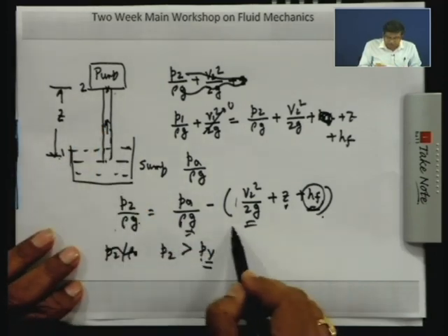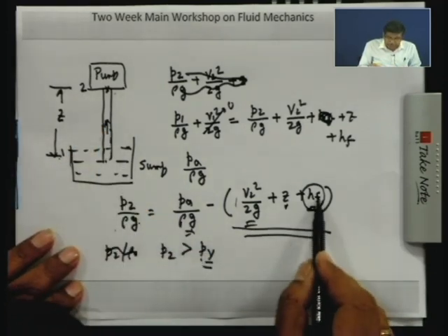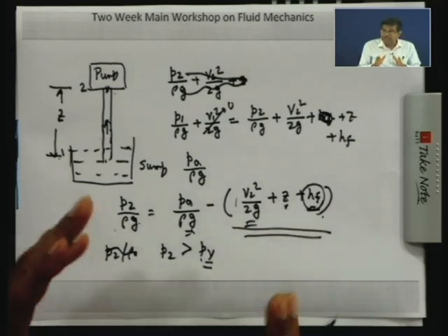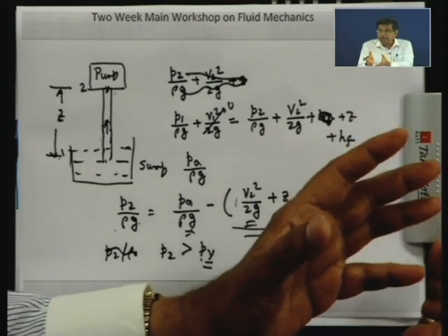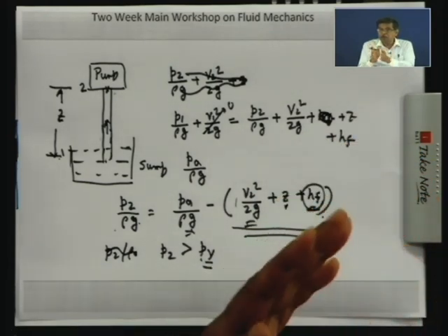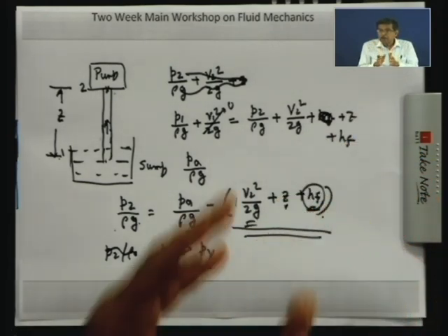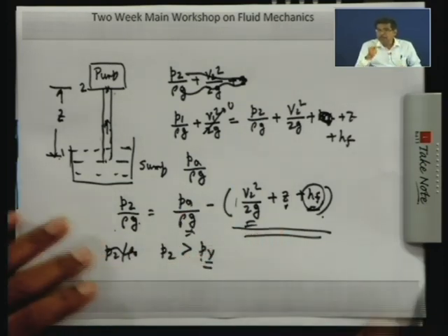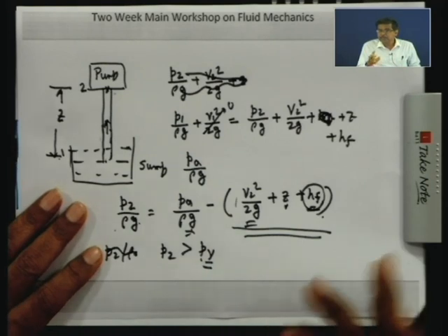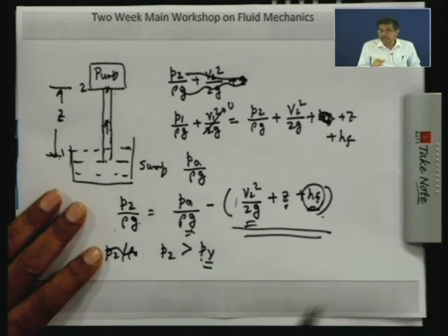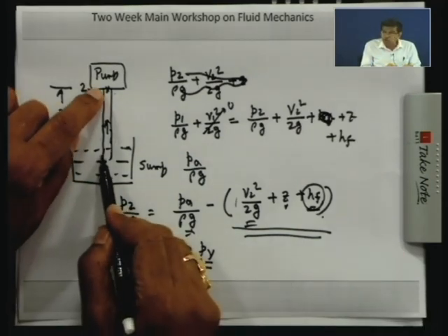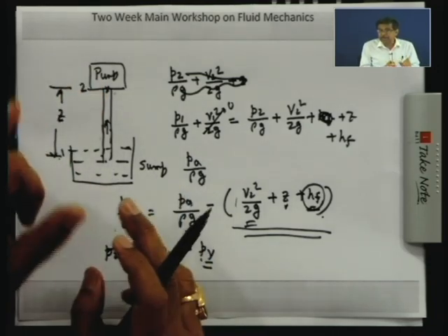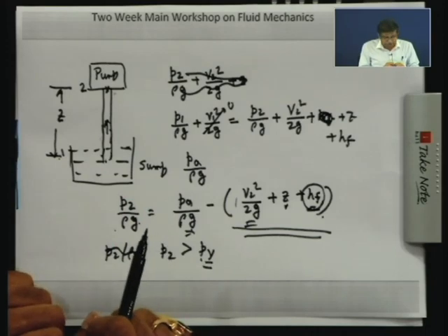So this is the basic concept, that these parameters have to be checked carefully so that cavitation does not occur, and that is the reason when we pump water from a well, we do not place the pump on the top, so that a big pipeline going to the well will start pumping the water. This will create cavitation. We have to check this height should in no way be higher than the height of water corresponding to the atmospheric pressure.